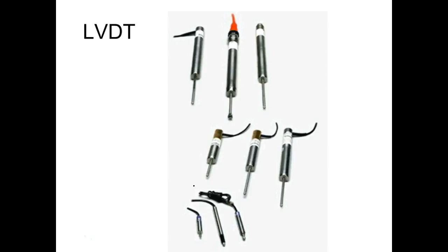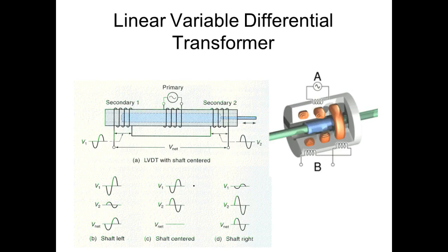Is the wire insulated or just on top of each other? Back up your picture. See the wires, the one in one direction and then the one in the other direction. Oh, they touch. What do you mean touching? What we use in transformers is a type of wire called magnetic wire. What we're trying to do is get the maximum coefficient of coupling. So yes, it's insulated, but it's insulated by what? Very, very thin coating.